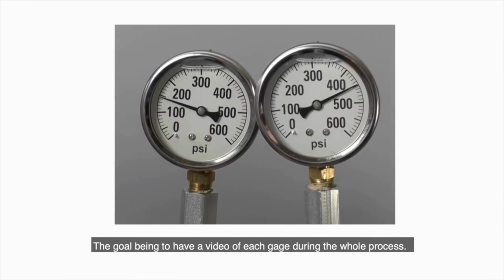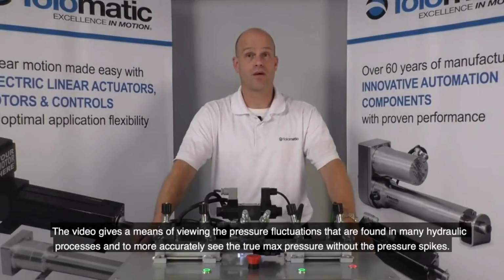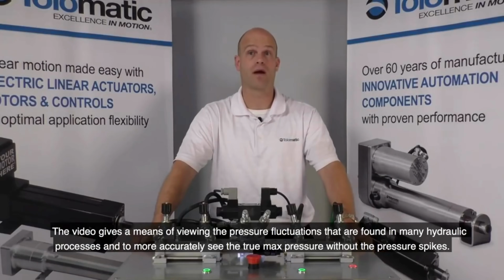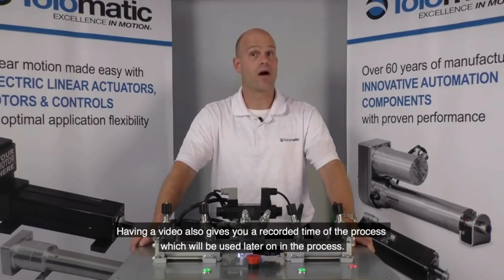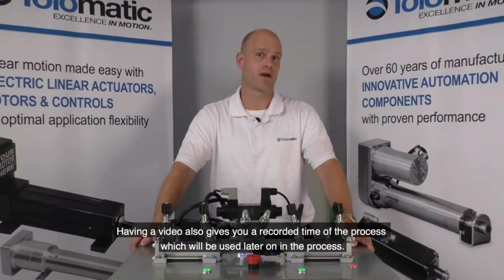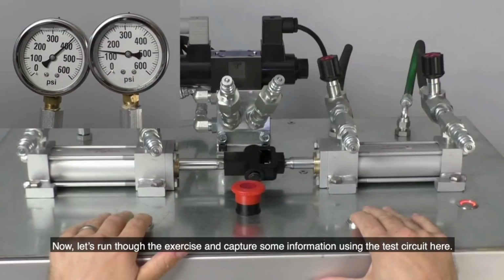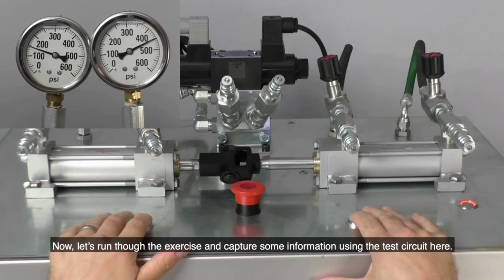The goal being to have a video of each gauge during the whole process. The video gives a means of viewing the pressure fluctuations that are found in many hydraulic processes and to more accurately see the true maximum pressure without pressure spikes. Having a video also gives you a recorded time of the process, which will be used later on in the process. Now, let's run through the exercise and capture some information using the test circuit shown here.